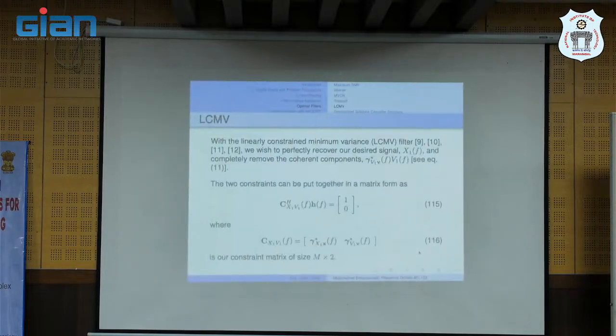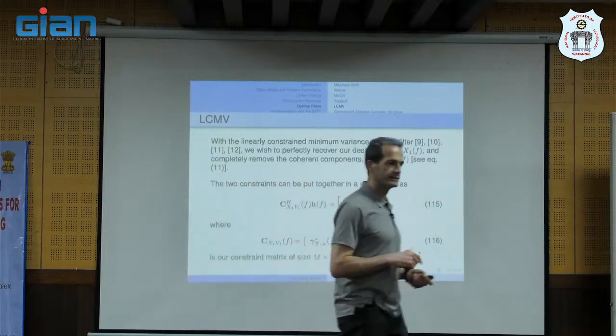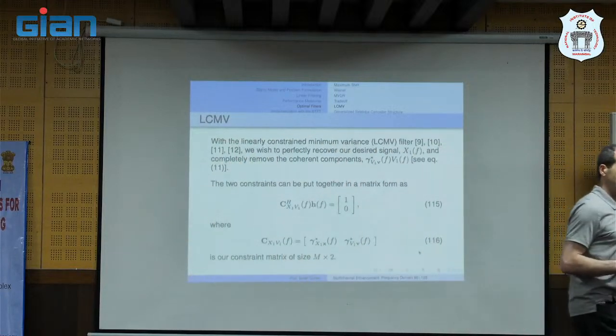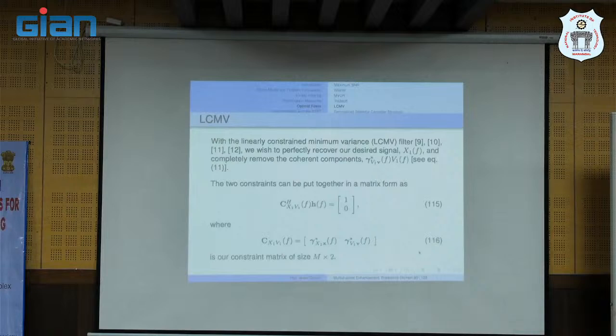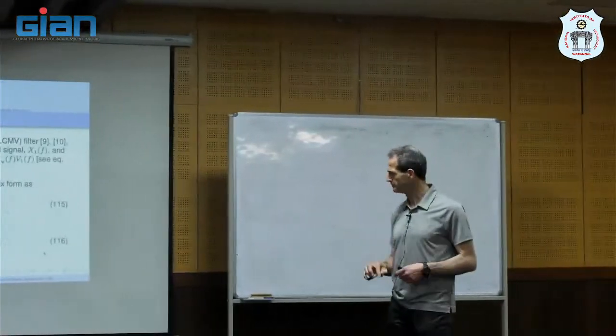Okay, so we want to move on to LCMV. Let's explain what LCMV is, and I will give you some motivation. The motivation will come from what we talked about with MVDR. You can view LCMV as an extension of the MVDR, the minimum variance distortionless response.